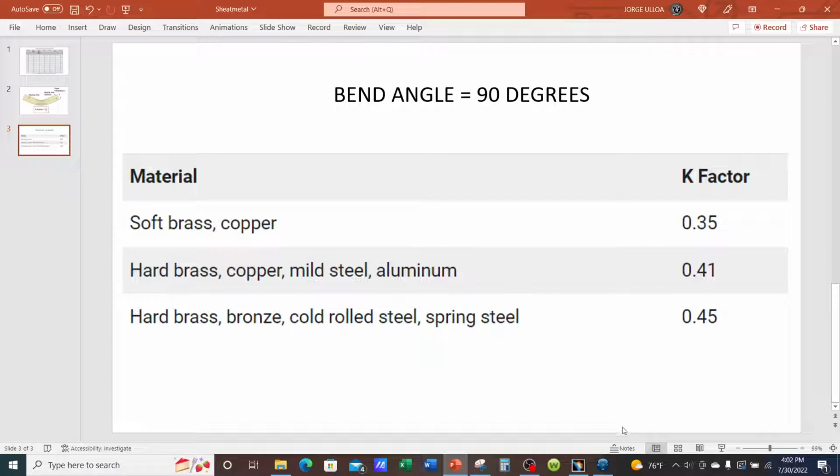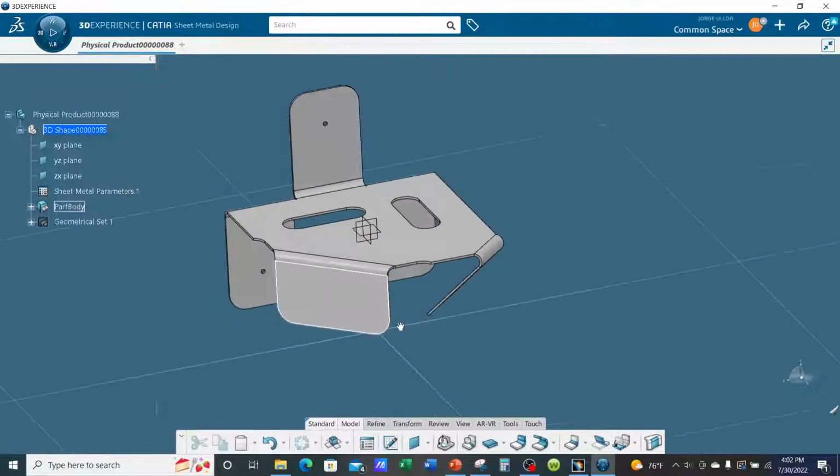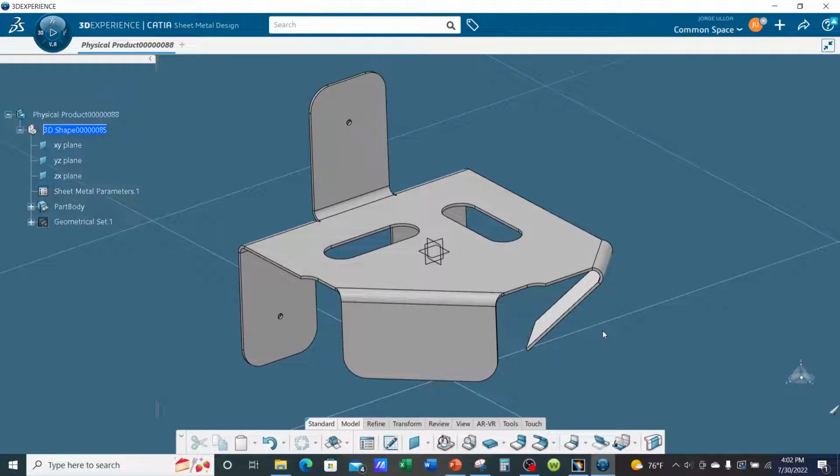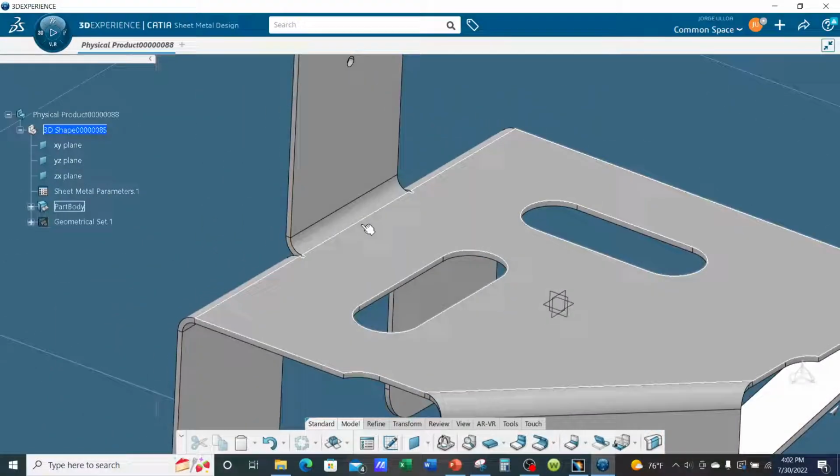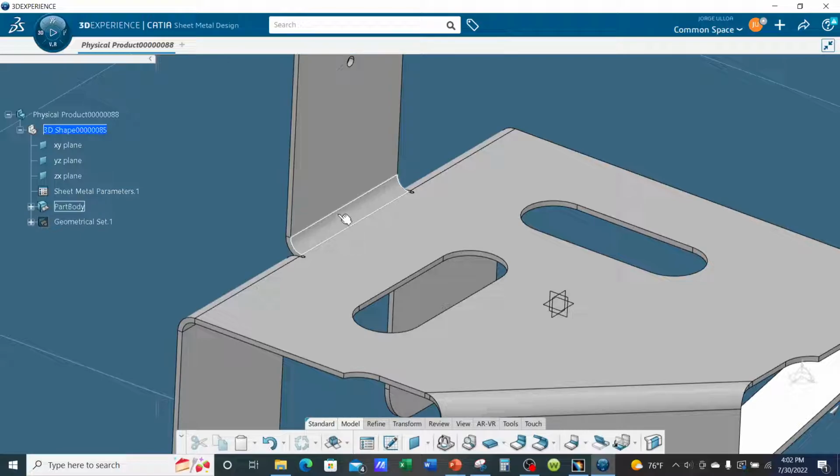Once again, typically at work, when I'm ready to create a piece of sheet metal from scratch, I will go to my parameters, and then I'll link it to an Excel spreadsheet where I'll pick my material. Let's say aluminum 6061 T6. I'll pick my thickness, 0.063 for example, and that's in inches. And the table will automatically pick the smallest bend radius allowed.